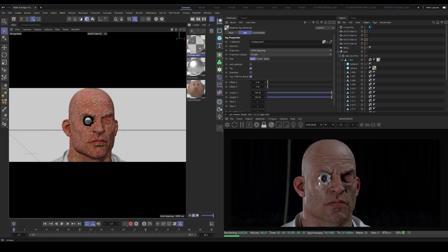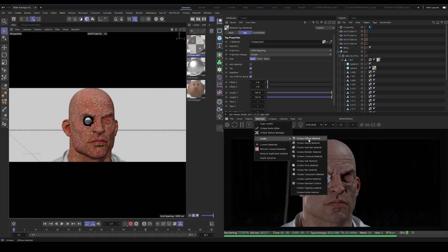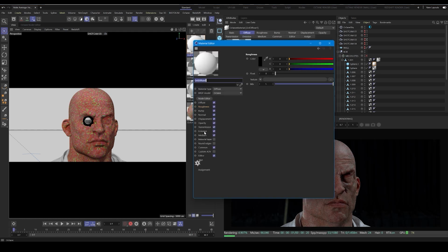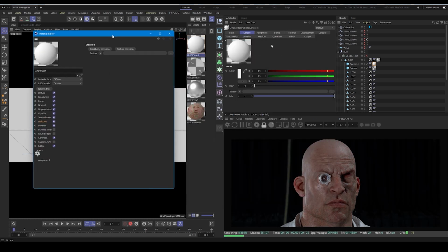So now this is transparent, and I'm going to change the material, I'm sorry, of the very center sphere here to something emissive. Material, create, diffuse, drag and drop into here, and make it an emission material.